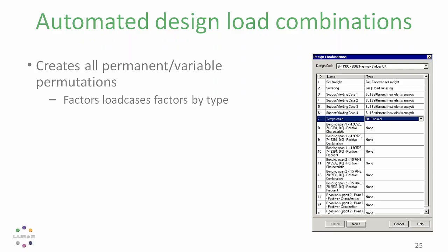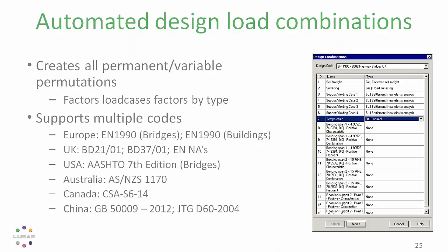So load cases within this are factored by type. Once you've described the type, LUSAS then deals with them according to the code of practice. This supports multiple codes, so again, North America, Europe, and various Asian codes are supported, and these will continue to be added to.